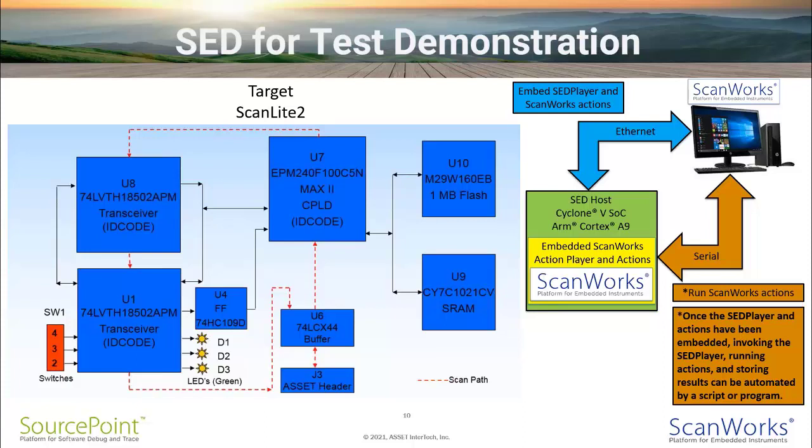So the commands don't need to be issued from a PC, and don't need to be issued from ScanWorks. ScanWorks is totally running and embedded on the SoC, and the commands can be issued directly within the SoC as well. I just wanted to drive that point home.